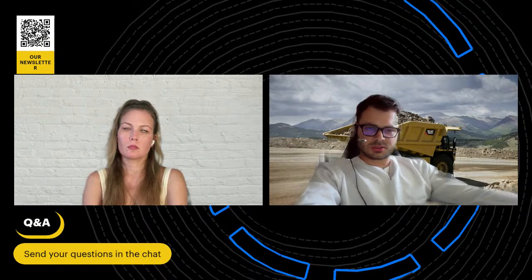If we have watered areas, of course we need trenches. The windrows should be everywhere. Then a safe distance between trucks when they are moving. Then ditches or a wider roadway, and of course the sliding wedge, as we said, the prism of possible collapse. All of these parameters dictate the minimum road widths. But I think the most important thing here is the roadway width, because it depends on the width of each truck.